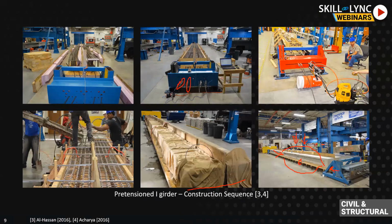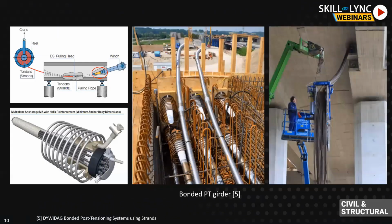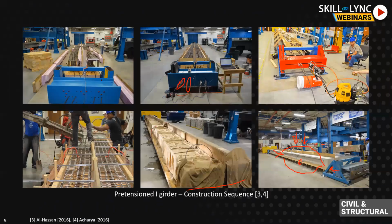So this was about bonded prestressed concrete. Since we bond the concrete and then we release the strand, that's why it's called bonded prestressed concrete. Now let's look at how PT looks. The concept of PT is similar, and we can understand it through this picture. In actual bonded pre-tension, we directly pour the concrete onto the strands. So these strands directly come in contact with the concrete when we pour.